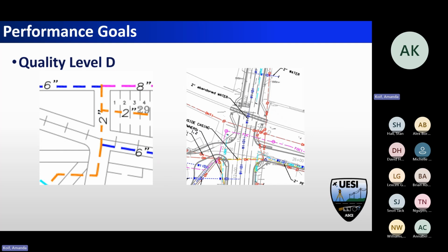What would be a good response to someone requesting that, and letting them know about the vulnerabilities of not letting your scope at least cover the crossings that go to the side that they're interested in? So with that, we always say we're going to have to go on the other side of the road. Sometimes we have to go outside because it's part of a utility network, where you don't know what's crossing. We still have to do our records research for the other side to see if anything can or should be crossing. We need to go open the vaults and manholes on the other side of the road to make sure nothing's coming in.